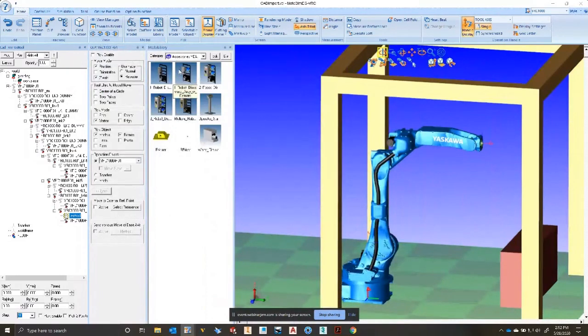This is a library, it's on your hard drive. It has a collection of models that are already made up for you. We have additional models on our website you can download, and you can put them in your model library, which you can, by the way, define the location either in a hard drive or a network location. Oh, fun fact and side note, please. You can define your model library anywhere in the network. Please do not open your simulations from a network drive. Due to network lag, it can cause an issue. It looks scary. It's not, but we have seen it with a robot.